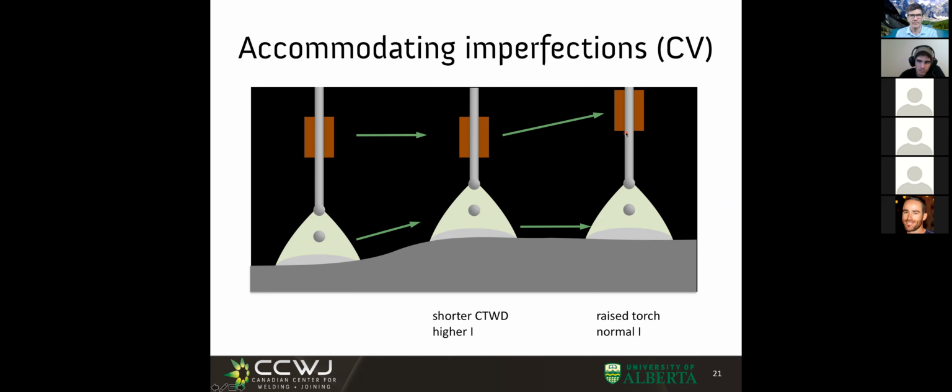And this is fantastic. When people are doing internal cladding with flux core electrodes, they need to put a very long boom that is very flexible inside the tube, right? And the way they regulate that, they change the standoff of the torch from way down at the tip of the tube, but they know if they are too close or too far because they are sensing the current in the process. Super amazing, super amazing. Let me tell you more.